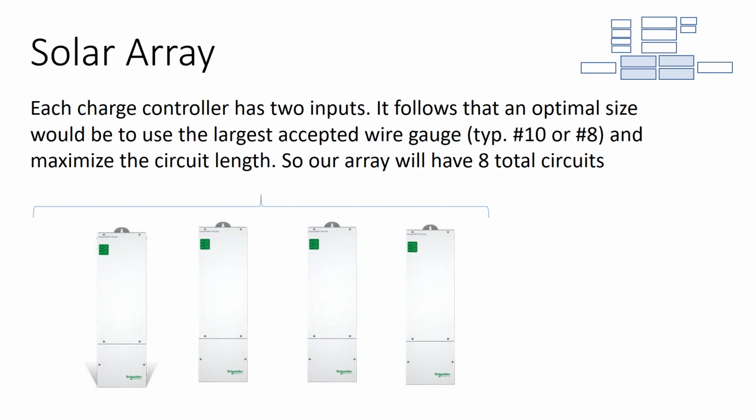You have a custom design for every rooftop, and sometimes that means that your inverter is oversized or your inverter is undersized. I think it's a good design practice to look at the maximum capabilities of your individual components and try and max them out, and then work your way backwards from that.